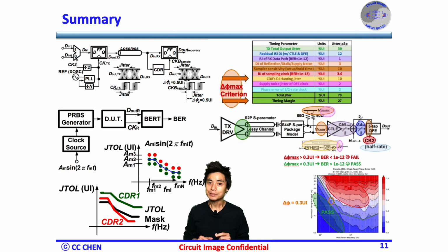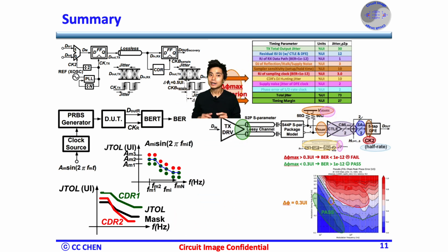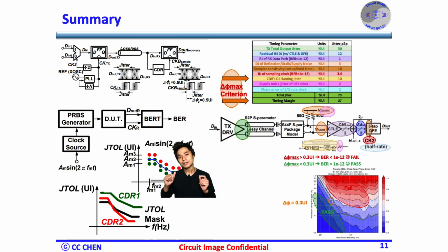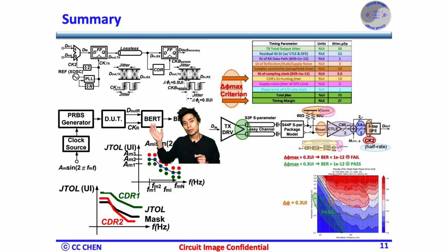Here are the summarized images of why we need a pseudo jitter tolerance in a CDR design or verification. The SerDes link will provide a better transmission quality with a low bit error rate, or equivalently a good jitter tolerance. Therefore, most standards even specify the jitter tolerance mask for the ecosystem to follow. Even though testing the jitter tolerance through the bit error is doable, it's impossible to run the jitter tolerance simulation in any simplified CDR model for design or verification.